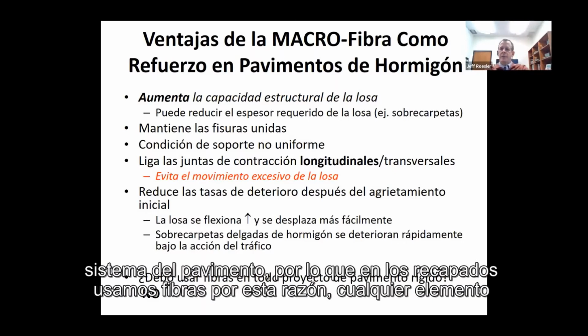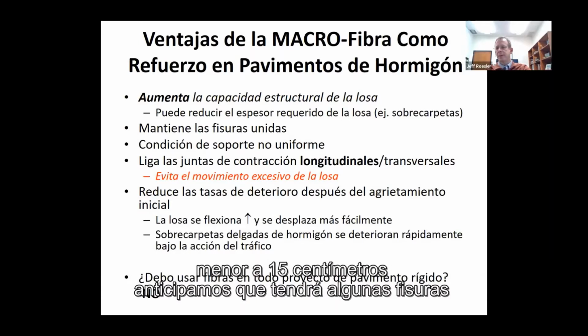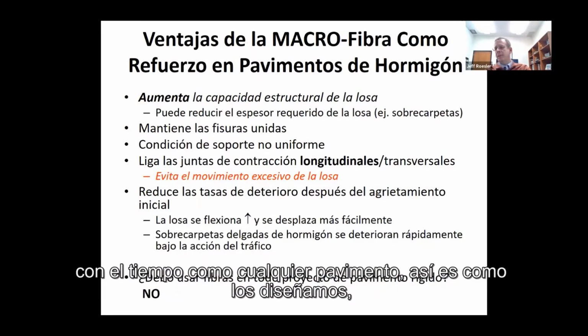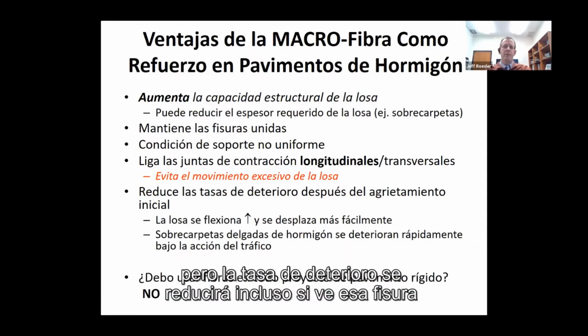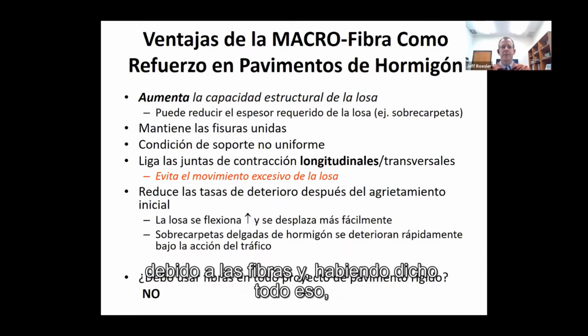So in overlays, we use fibers for this reason. Anything under 15 centimeters, we anticipate will have some cracking over time, like any pavement. That's how we design them. But the rate of deterioration will be reduced even if you see that crack because of the fibers.